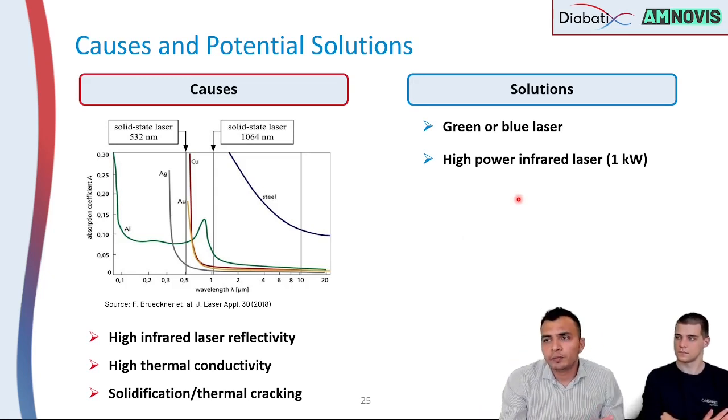Because of that increase, the copper powder melts and you create a keyhole. This idea is based on using the keyhole feature of the melt pool. A keyhole is basically a hole inside a melt pool. The laser goes inside and gets trapped within that hole, and it can have multiple internal reflections and has no way to escape other than absorption.